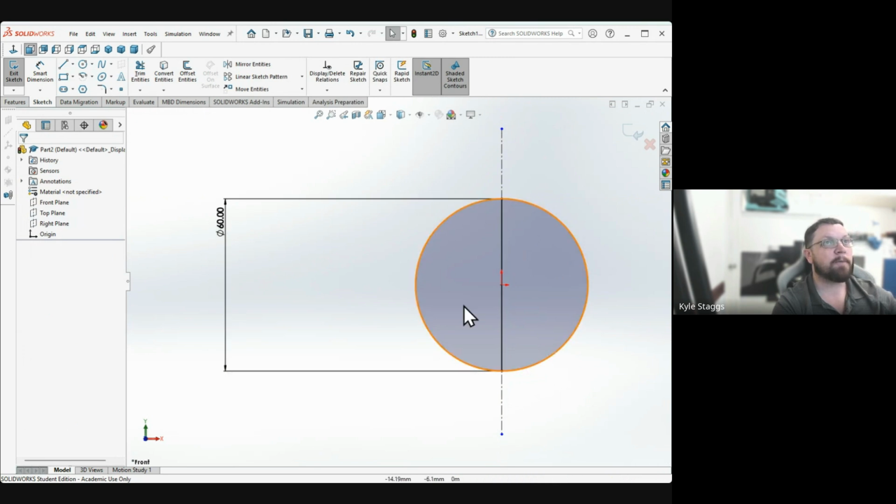If you're going to do a revolve on a shape, you need to use half the volume, because it's trying to revolve the shape by creating a volume, but it then creates a volume 2 different times when it goes 360 degrees. The only thing that you could really do without having a dividing line is maybe about 90 degrees, because it would understand a 90 degree slice of a sphere.